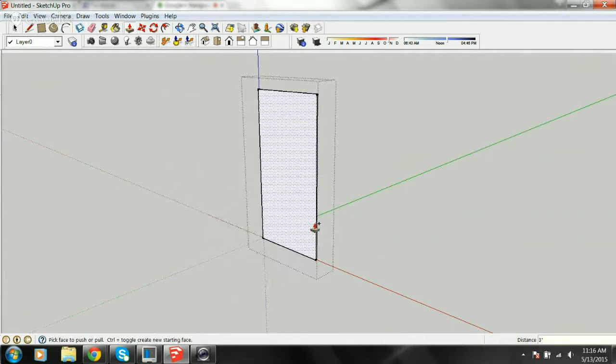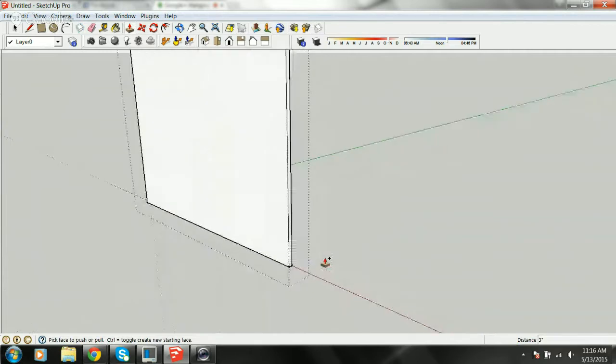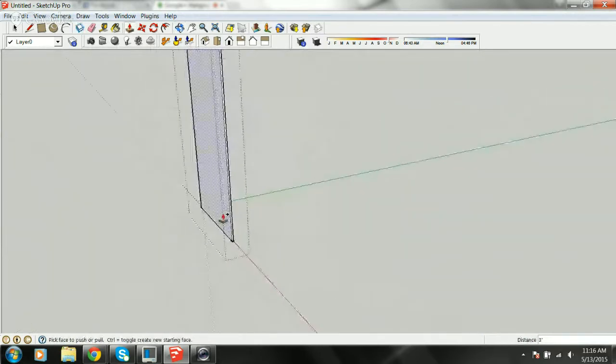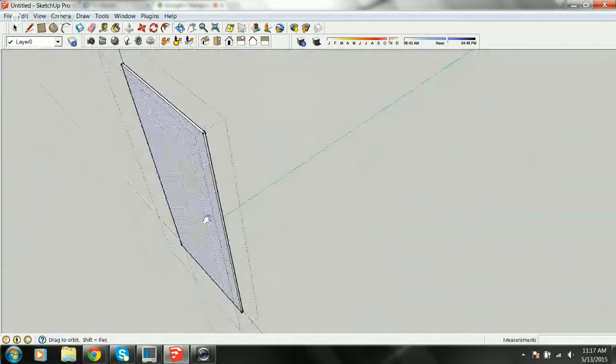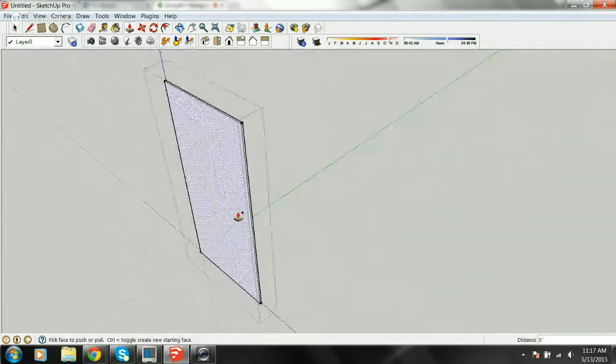Okay. I'm all about the precision side of things. I don't like to guesstimate when I'm modeling. So now I have a 3-inch thick wall. That's the part that really destroyed me, was this guessing part, and I'd try to find out where to put the, it's just a process you have to see before you do. Well, right. And the default in this distance button, you don't have to go down and type in it. You can just type your numbers. Oh, okay. For inches, you don't have to type the inches sign. Just type 3, 6, 9, 12, 24, 57, however many inches you want, and hit enter. While you're pressing the control button and pulling, you press 3 and it goes.